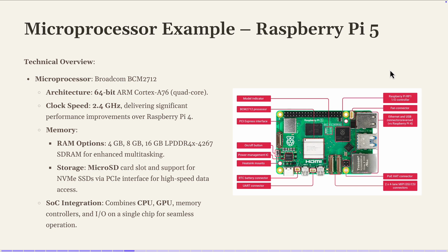And then we convert this value to the correct temperature that comes from the sensor. So the ADC will convert the signal into a value between 0 and 1023, which is like a value that will tell us about the temperature or the humidity level that comes from the sensor.